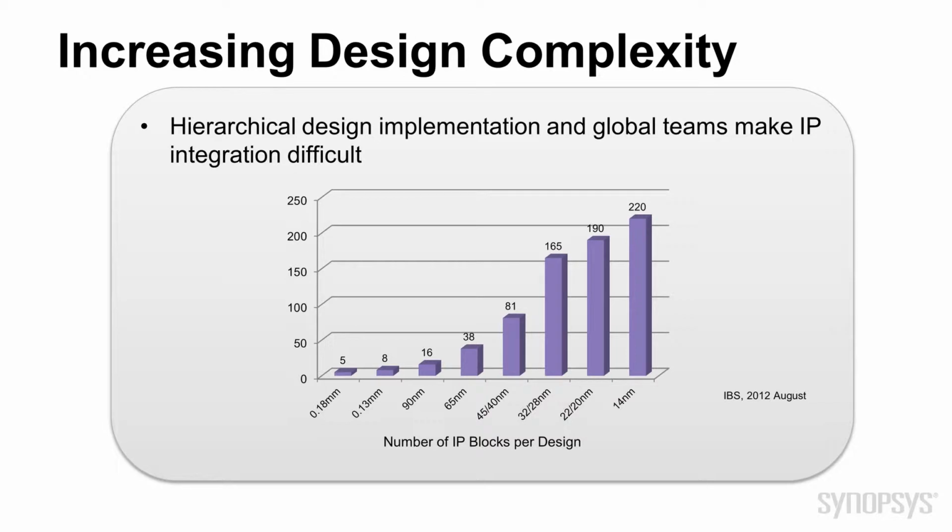Finally, large designs are often worked on hierarchically, with global design teams owning different portions of the design, making it necessary to have standard and unified interfaces at each design hierarchy for easy integration at the SoC level. Designers must choose a test solution that is capable of handling large hierarchical designs efficiently while minimizing test time and power consumption in order to meet test cost and design requirements.